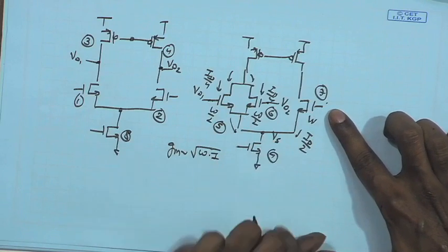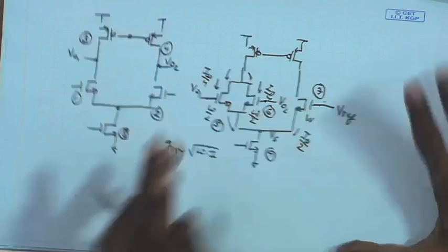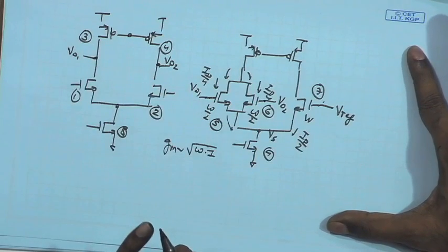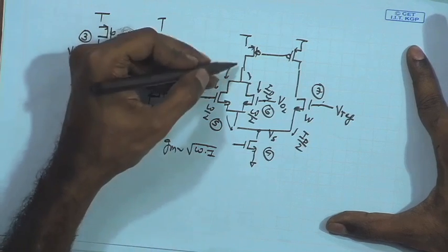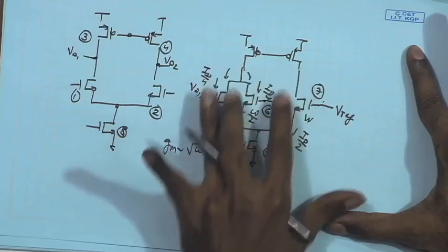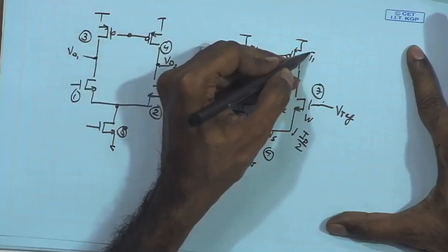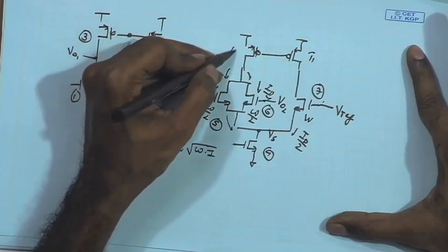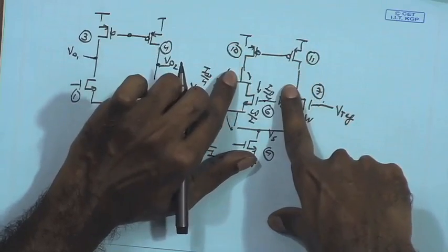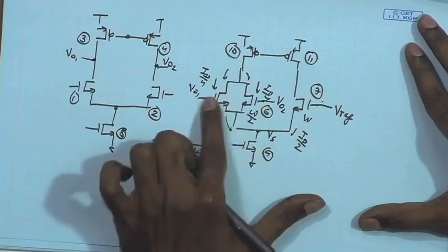Suppose there is some small signal Vs coming over here. This is our reference signal Vref, and I want my output common mode of the differential amplifier to be set equal to the reference signal. As a result, if I look at the small signal current combination flowing from these two transistors, let me call this ID11 and ID10. So, if I look at the small signal current flowing through these two transistors provided by these two pull down devices, I can sum the small signal current flowing through these two.